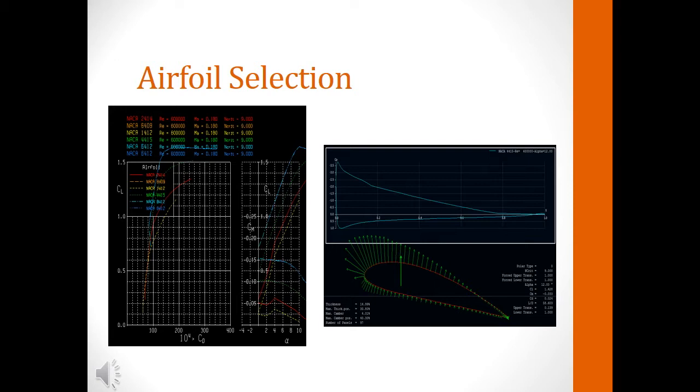You can see that the curve has an extremely high CL over CD, which increases lift. It also has a very high lift coefficient for increasing angle of attack. The right figure shows the pressure distribution of our airfoil run on XFLR5.